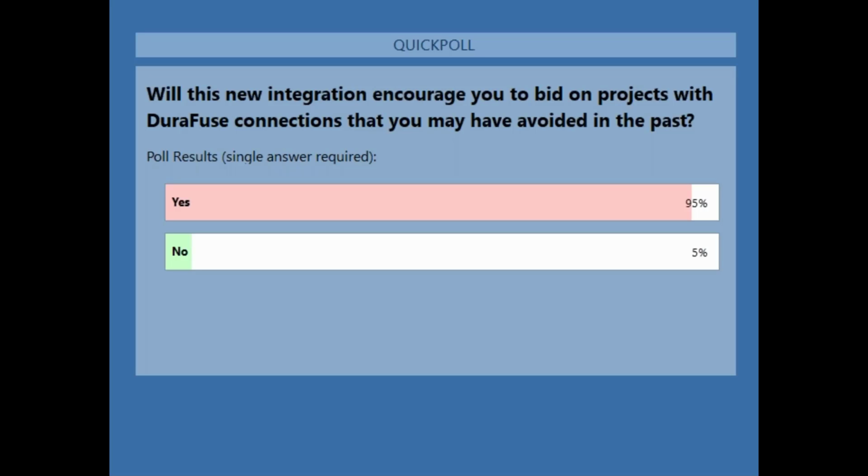I don't know that that was demonstrated in the demo, but typically we will have stuff framing into the orthogonal direction of the column. Generally, those attachments are being made to the cover plates that we're putting onto the columns rather than to the column web itself.